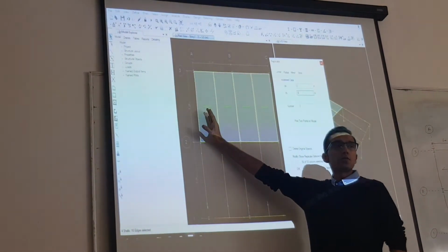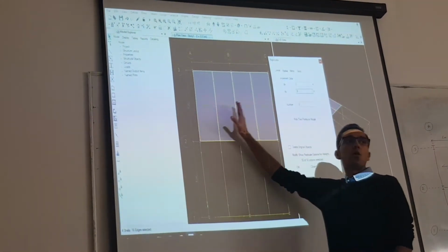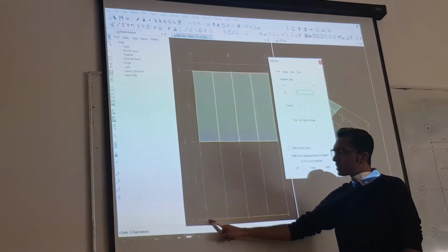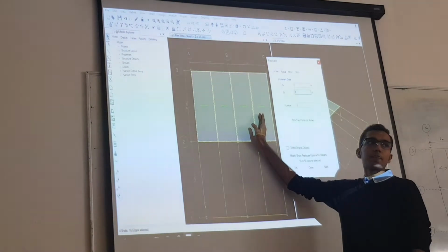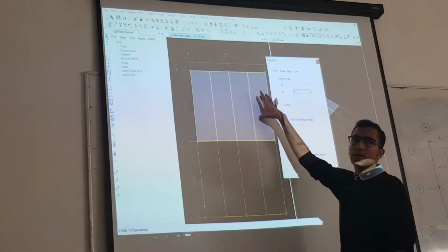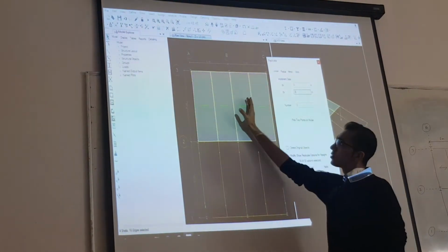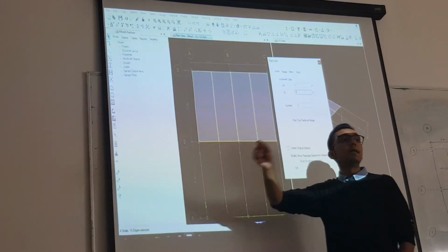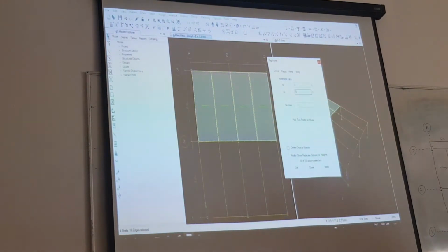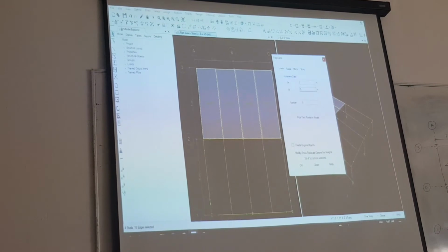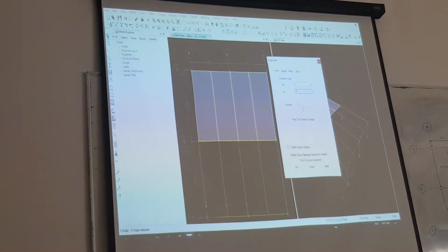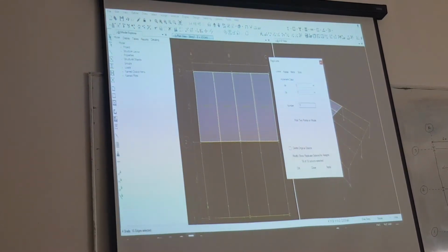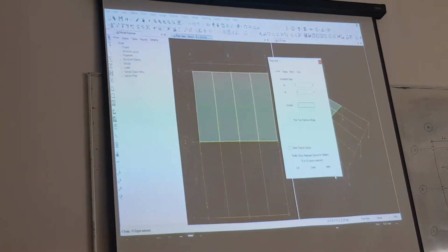If you are going to replicate this slab on the right hand side, which is plus x-axis, you are going to write plus 3 meters. But if you want to replicate on the left hand side, it means minus 3 meters. Okay? So write minus 8 over here, and we are going to replicate only one time, otherwise it will go beyond the grid system. So click on apply